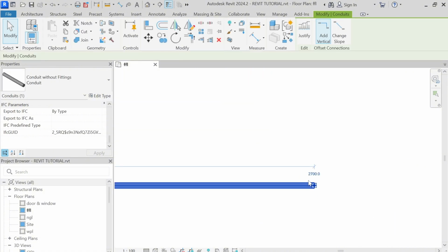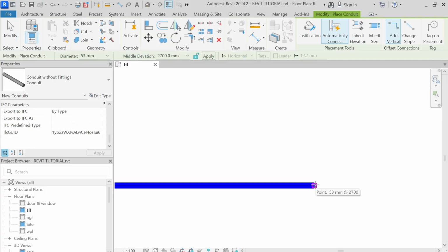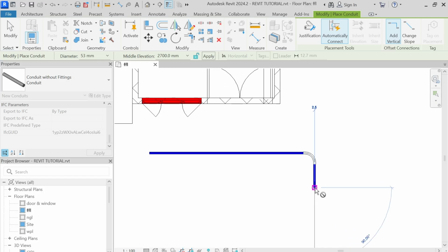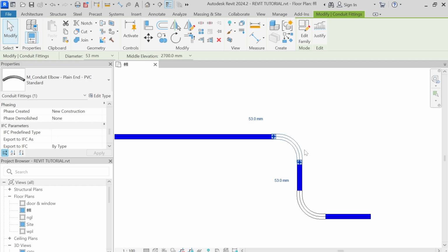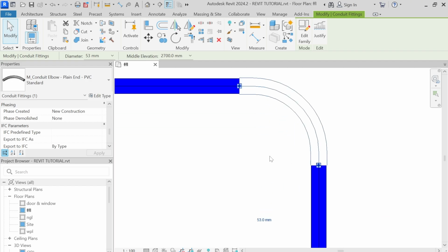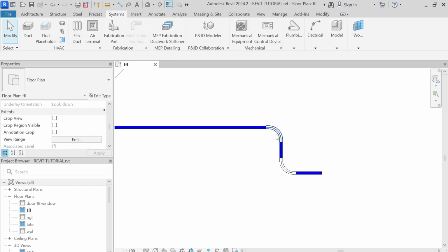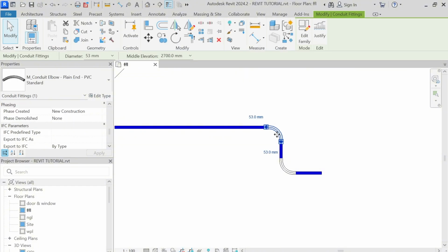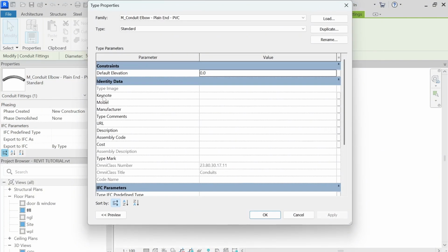So whenever you just say create similar, you'll see S on your keyboard. Whenever you're drawing the conduits, it's gonna be turning into blue. But now, what is very much confusing for me now is my fittings in here. You see, let's try see. Just type comments in here. Just say conduit fitting. Conduit fittings.